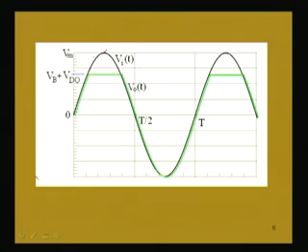So, this is a typical example of a constant voltage drop model considered for the diode, and this is a simple clipping circuit, which clips a portion of the waveform; the upper portion is clipped. We can design different clipper circuits according to our need.